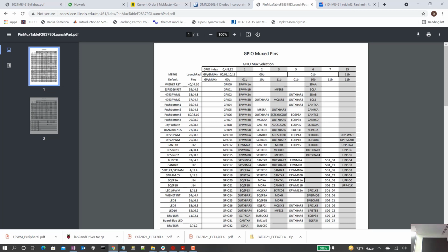So at the beginning of labs, I'll tell you we're going to need to use EPWM 2A and 2B. We're going to need to use SPI pins, SPI-A clock, SPI-A data, or actually it's called master in, master out, all this stuff. We'll get to those serial port pins. And I'll give you little tips, of course. We'll be using GPIO 29, say, for the UART's transmit data A pin, or something like that.